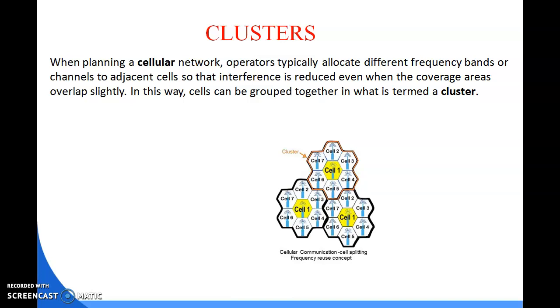Then another scheme is known as DCA, the Dynamic Channel Allocation scheme, which has been implemented in this cluster also, but with dynamic assignment of frequencies to cells. The danger of interference with cells using the same frequency exists. The borrowed frequency can be blocked in the surrounding cell. So it is a complex technology.